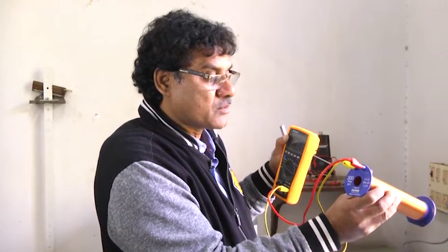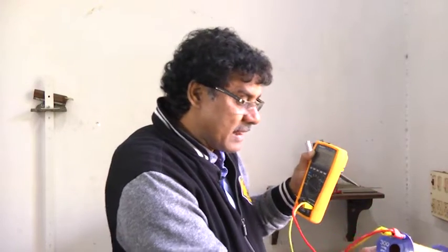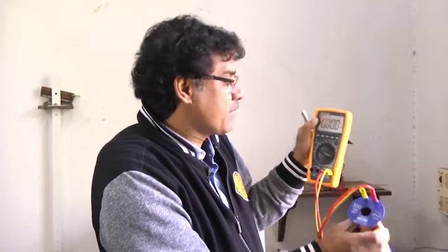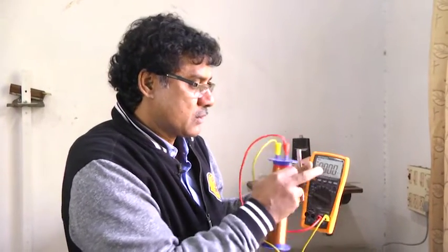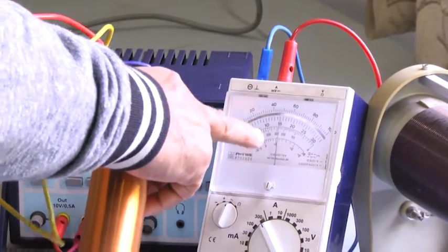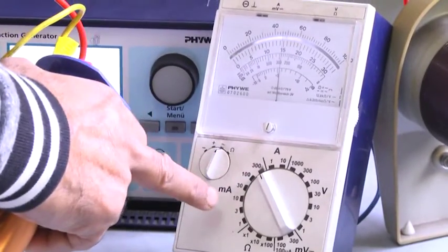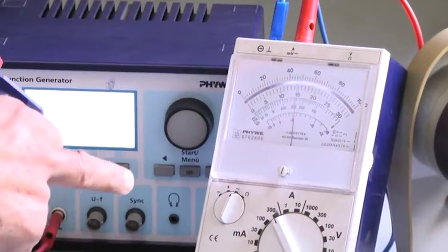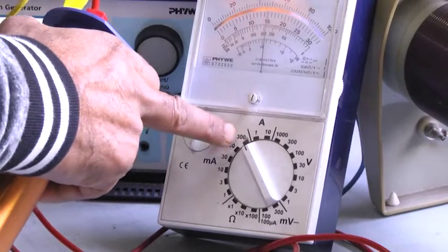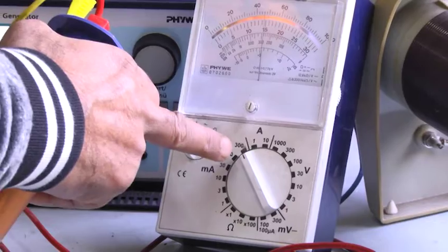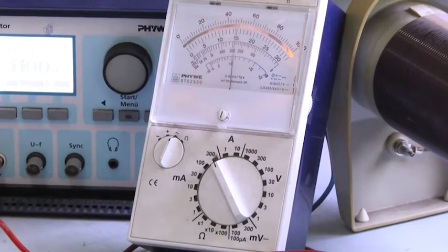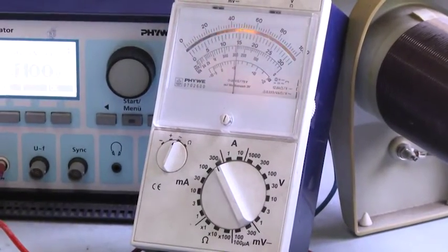Now I want to place this coil in the magnetic field, where the magnetic field is changing with time. There should be an induced e.m.f., an induced voltage, and that voltage I will get in this voltmeter. The current is set; you can see the reading is in the range of 300 milliampere, so you have to use the 0 to 30 scale. That means this is not 15 milliampere, it will be 150 milliampere. So the current I have set is 150 milliampere.